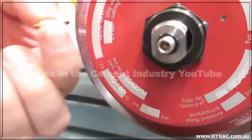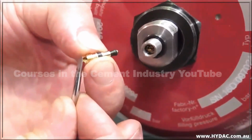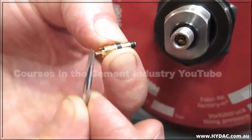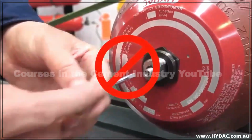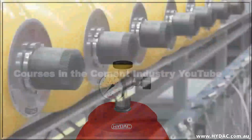The accumulator gas valve will be opened and closed by pushing the valve plunger down. This will be operated by the center screw of the A3 adapter. Due to the high pressures involved, this valve should never be opened by hand. Use only the correct equipment, that is, the Universal Charging and Testing Unit, and follow this process.